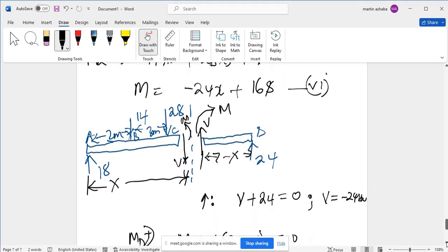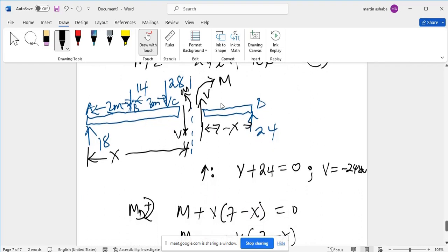Okay. Maybe to just wrap up, if this still was not clear, if you draw your free body diagram of the segment, you need to include also the earlier parts, the other portion. If we are considering CD, you see I've drawn the part for A, B, B, C, because those ones I already know the forces acting on them and I've already calculated the shear force. So I'm now on portion CD, so I just look at the beam from the left. So I go to between C and D, or I cut the beam. So if I cut it at that point, then I will have C and D now separate, okay?